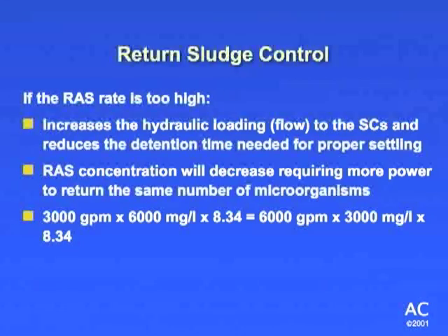And again, where would you check, like on your draft tubes? You check right up at the ports. You can take individual samples and do a sludge spin down, so you can make sure your ports are set properly. Usually once you have them set for your flow regime, and this will be when the clarifiers get commissioned, once they're set, you only have to go back and routinely check them when you're suspecting a problem. After a while you can tell by looking if they're returning good, if they're plugged or not.